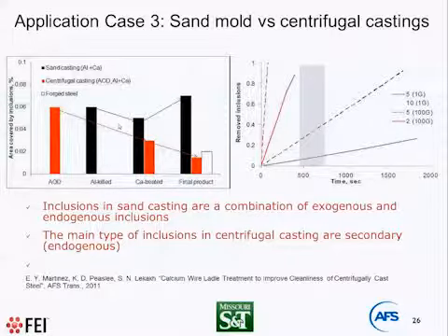But when we apply centrifugal forces, which increase g approximately 80 or 100 times, we have the possibility to refine the melt by huge centrifugal forces. The red line shows the solidification time. Before solidification, we can remove a significant part of the inclusions. As a result, casting produced by the centrifugal method could be significantly cleaner than sand casting, and also could be cleaner even than forged steel.